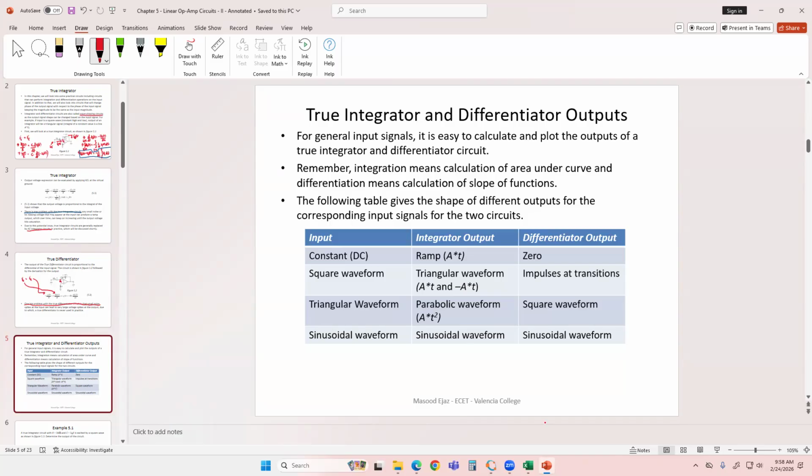an up and down ramp, of course. So this is a square waveform. You're going to have a ramp signal going up. You have a ramp signal going down. So a triangular waveform, basically, output of the integrator. And the differentiator is just going to produce impulses whenever you have these changes. Because again, the changes are happening in a brief amount of time, right?